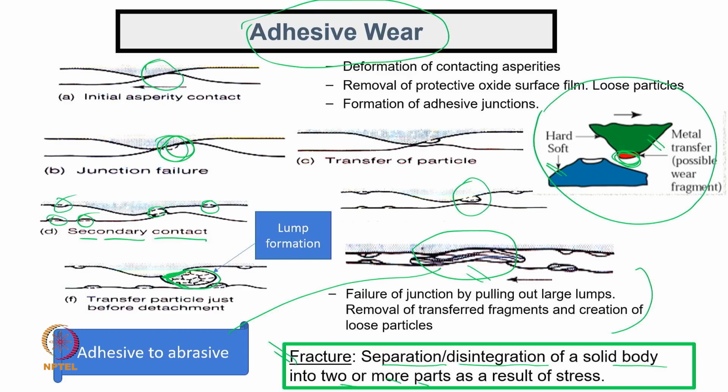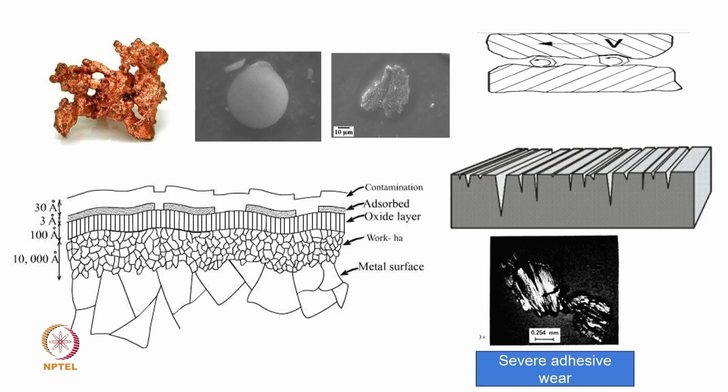and maybe say wear itself can really work with the fracture phenomenon also, but maybe at the micron level or the nano level, and we really require to collect the samples. So, we collect the debris and then look at the microstructure, morphology, pattern, and maybe chemical composition. Once we have that kind of information, we can really judge what is happening inside a system. So, it will impart more and more information related to failure well in advance.